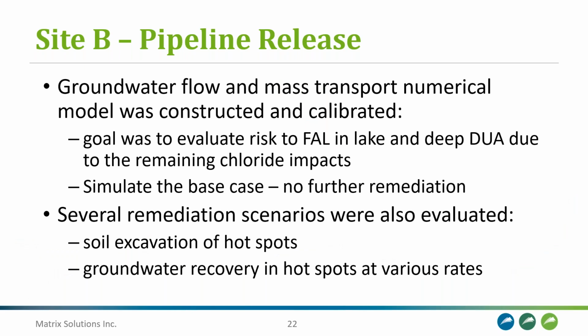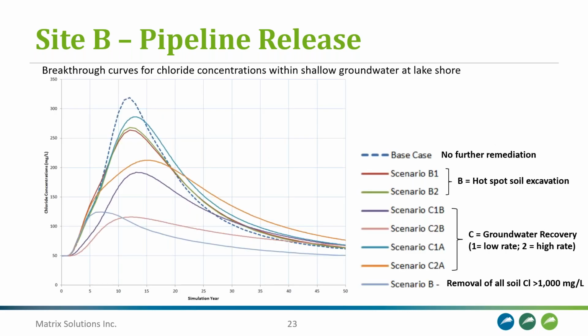So again, a groundwater flow and mass transport numerical model was constructed and calibrated, and the goal was to evaluate the risk to freshwater aquatic life in the lake due to the remaining chloride impacts. And so we went ahead and simulated the base case, which is no further remediation. And then other remediation scenarios were also evaluated, which consisted of soil excavation of hotspots, and then groundwater recovery via trenches in various different areas at various rates.